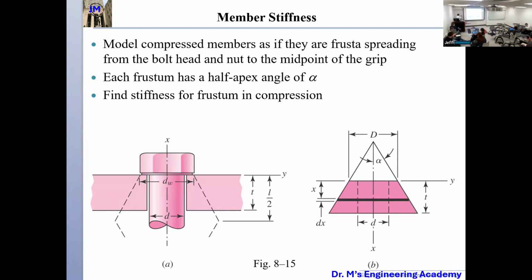However, this is Ro, and it is changing, like a cone: at the top it is big, but at the bottom it is smaller. So this Ro is changing, but this D is constant, and D equals 2 Ri, the inner radius. So Ri is constant, D is constant. That is the thread diameter because this is the hole.